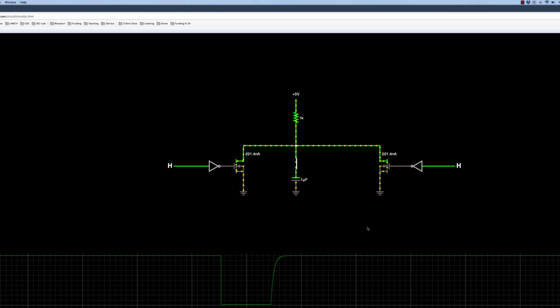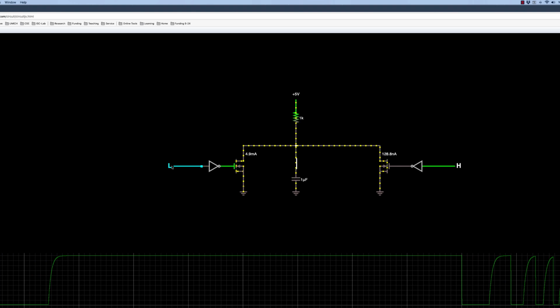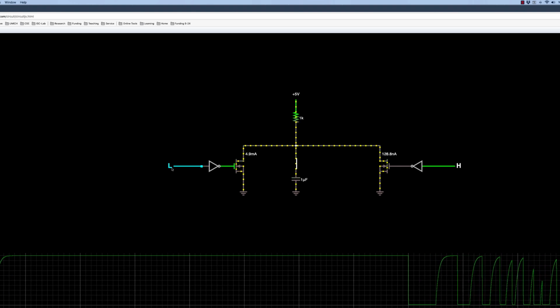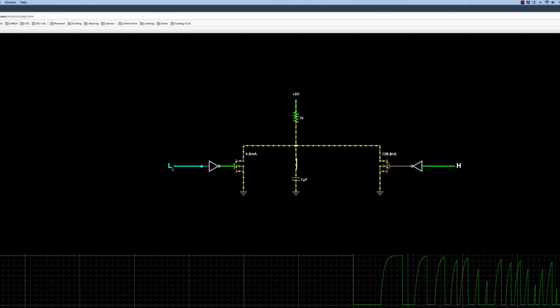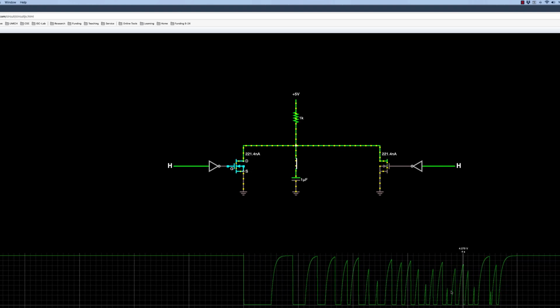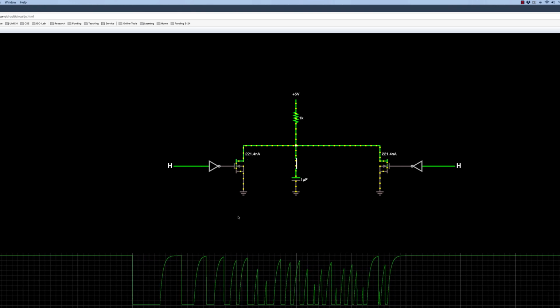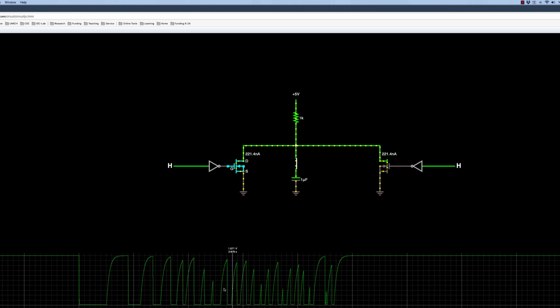Now, why this is important is this is the real limitation of an I2C bus. It's how much capacitance is on it. That's what's limiting speed. So we can see here, if I go fast, I'm trying to go fast, you can see look at all these corrupted data bits. Some of these didn't all go all the way up to the top, right? So I was trying to drive data as fast as I could in this bus, and bad things happen.